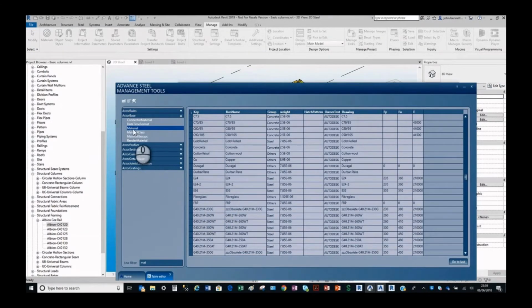And I'm looking here in the materials table. This is the materials table inside Advanced Steel, and you can see cold rolled there. You can see the bit I'm on about. It's the first column. It says cold rolled, no space. But the display name has got a space in it. And I fell into this trap.